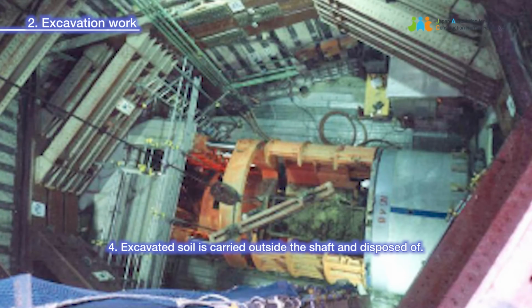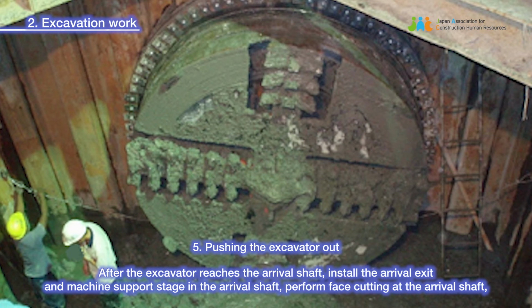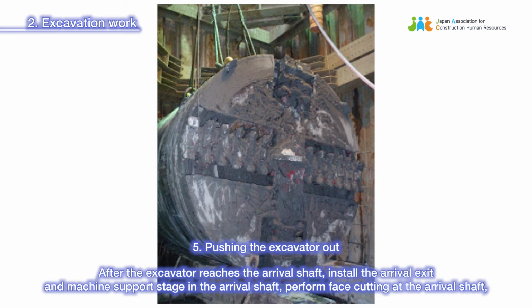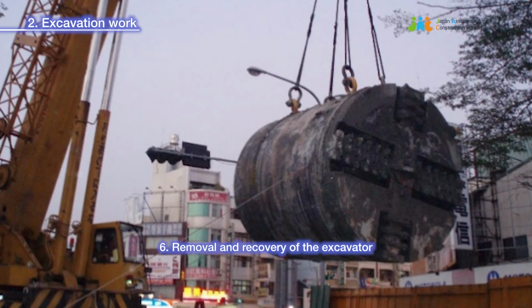4. Excavated soil is carried outside the shaft and disposed of. 5. Pushing the excavator out. After the excavator reaches the arrival shaft, install the arrival exit and machine support stage in the arrival shaft, perform face cutting at the arrival shaft, and push out the excavator while communicating between the start and arrival shafts. 6. Removal and recovery of the excavator.